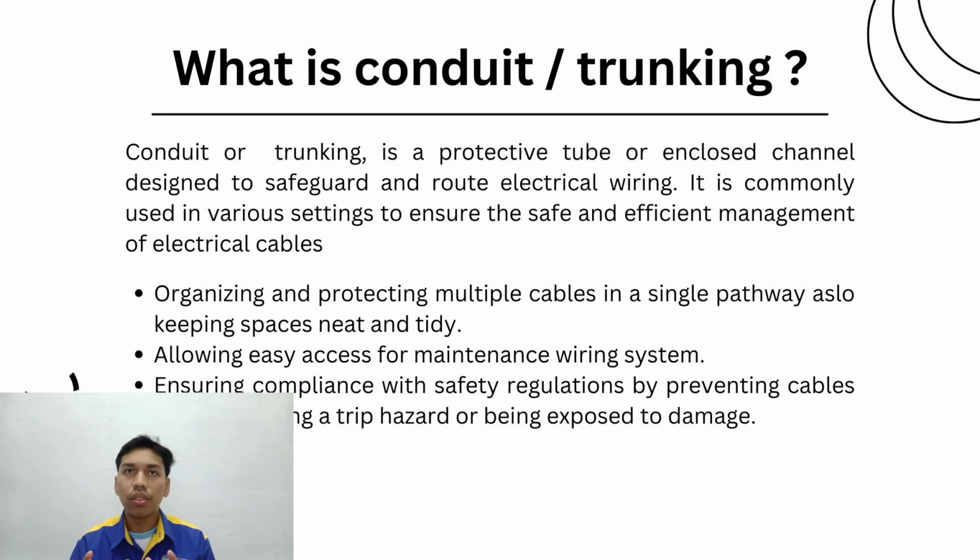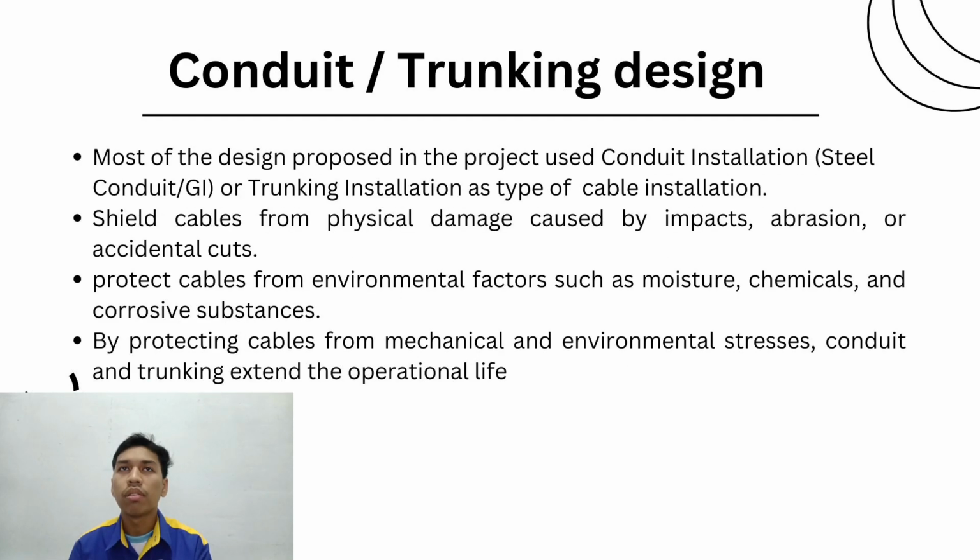It also ensures compliance with safety regulations by preventing cables from being a trip hazard or being exposed to damage. So for most of our designs, for the mosque and office, we consider using conduit and trunking, which is steel conduit / GI or trunking installation type to install the cable.